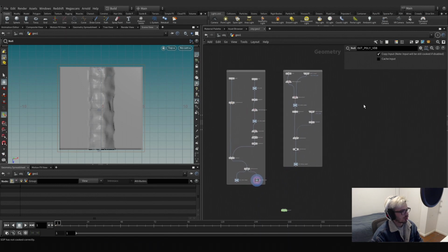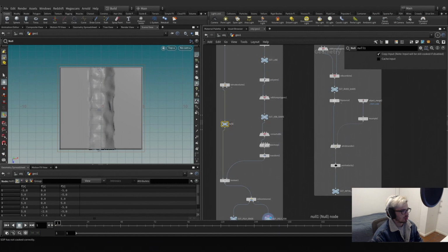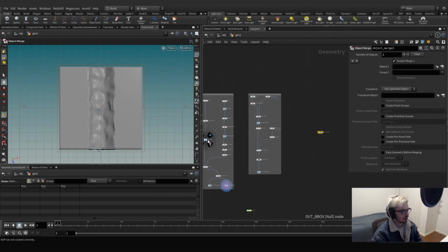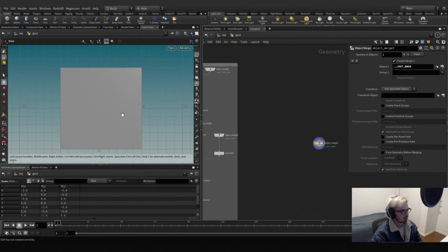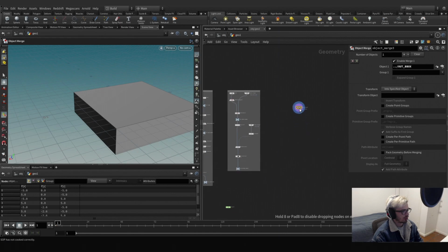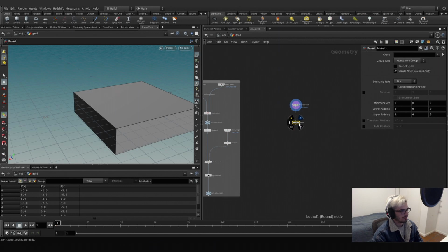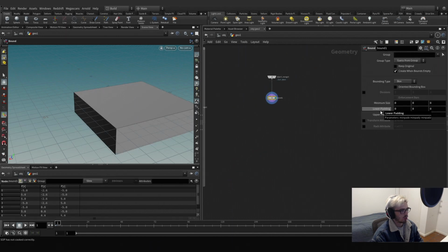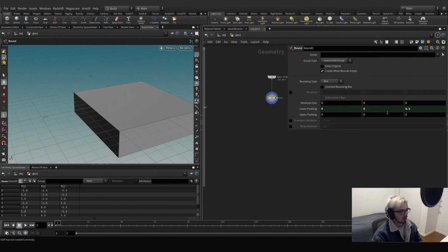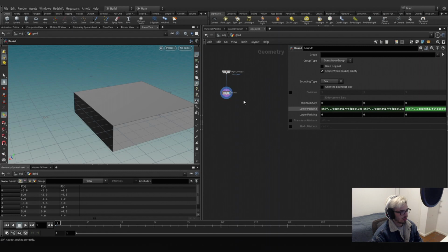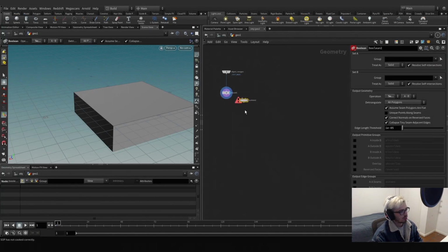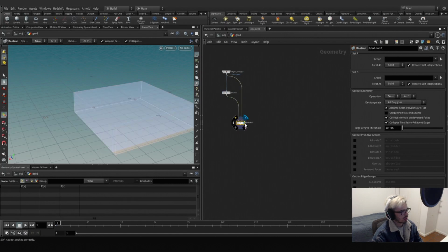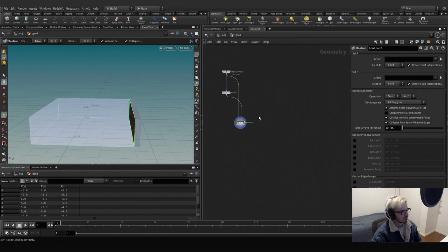Okay, so what we want to do now is the boundary layer. So let's make a new layer. This is where we're going to take our B-box and let's do a merge here with this shape around here. So we have our boundary box, right? So what we want to do now is to make a bound layer. In this case, we're going to just copy here and paste this here on the lower padding. Now we want this to be a negative number. And from this we want to have our boolean. Our boolean will basically subtract both of the things together. See, now we have this.